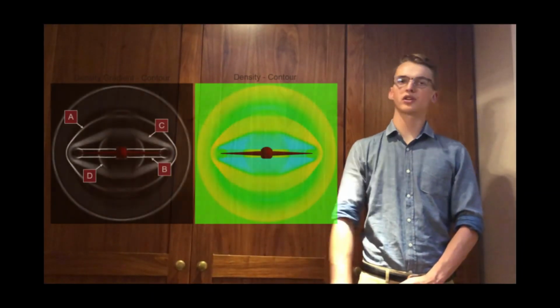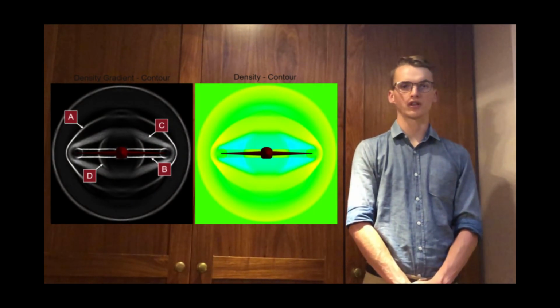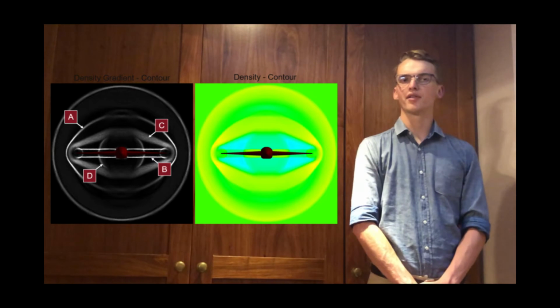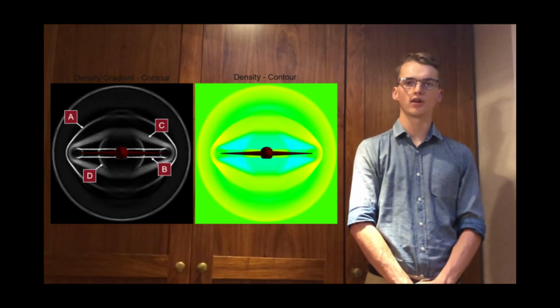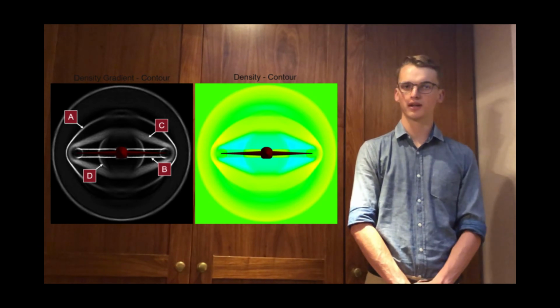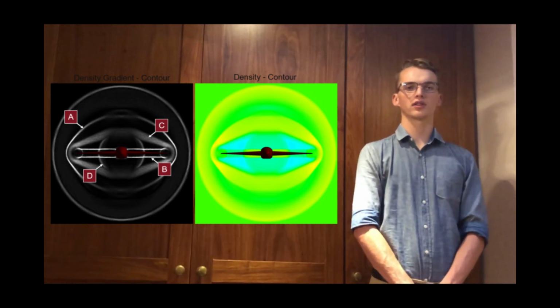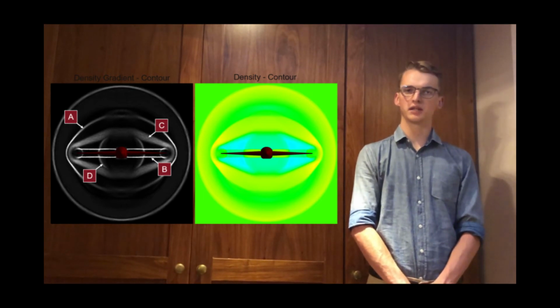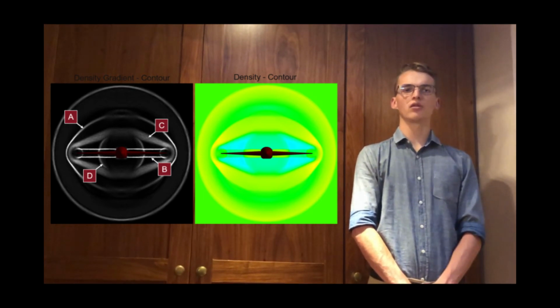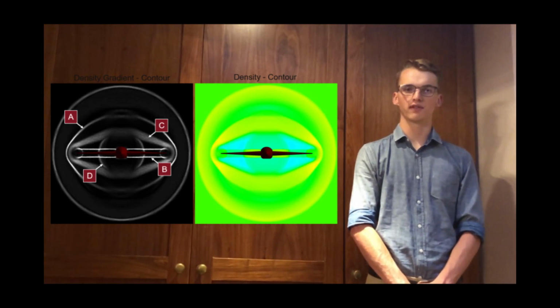This image shows another cross-section after the trailing edge of the wing. This cross-section demonstrates a bit more of the three-dimensional complexity of the flow around the body. The leading and trailing edge shocks, A and B respectively, are both visible in this image. The expansion from the vertex of the wing is also shown, indicated by the region C. All the shock and expansion waves are coiled around the tip of the wing due to edge effects.